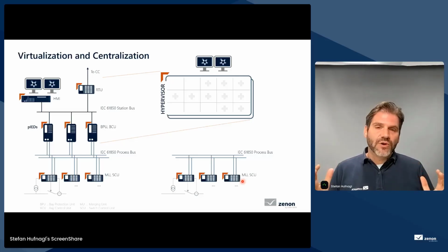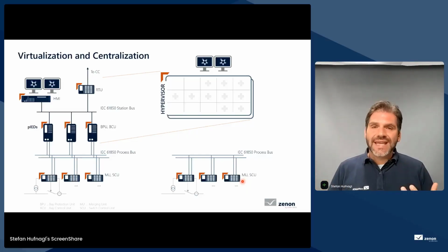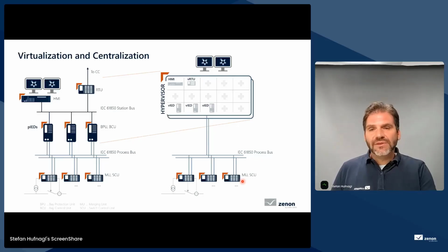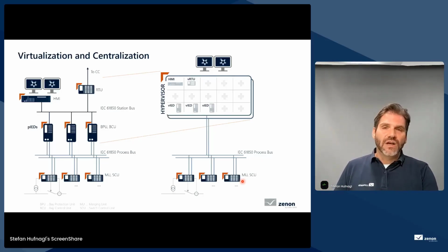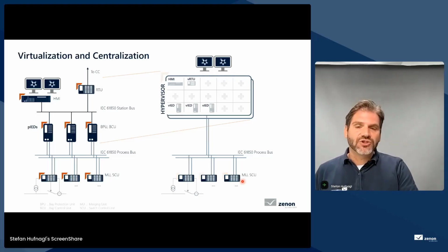So one platform which is able to run virtual machines on the one hand or containers on the other hand, and being able to host the functions virtually. As we had physical IEDs before, now it's virtual IEDs, a virtual representation of the same functionality. And the higher level functions like the HMI or the RTU could also be hosted on the same platform. That's the principle of centralization and virtualization.